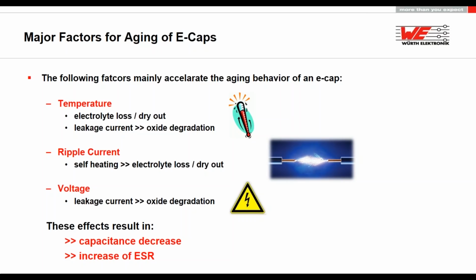So 440 would be okay, but if you go for higher ranges on a short-term basis, or even on continuous condition, you will damage the dielectric, because the dielectric is not prepared for such a high voltage level. Depending on the rated voltage level of the ECAP, it will be different how much voltage the dielectric can resist until a breakdown within the dielectric happens, leakage current flow will increase, and the dielectric will be damaged.